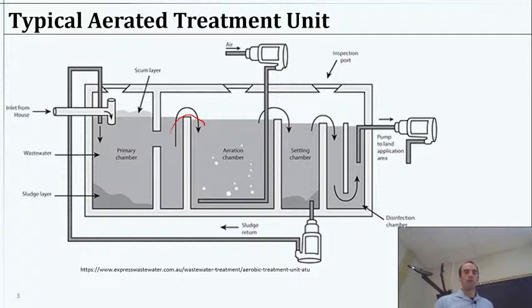And then after that, you let sedimentation occur, and from there you'll pump it out to where you're going to apply it to land. And then here you would have some sludge return to keep the sludge mixing in this area, to move it back to that first spot where there's probably more space, and that would be where you would remove your sludge or pump it out later.